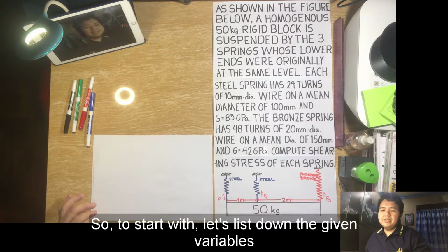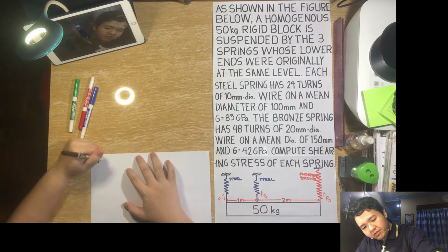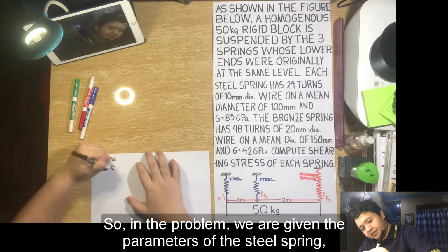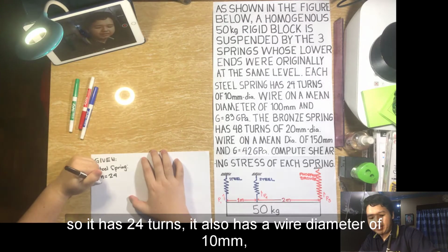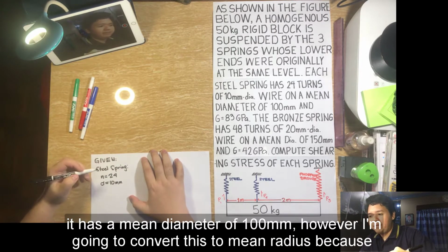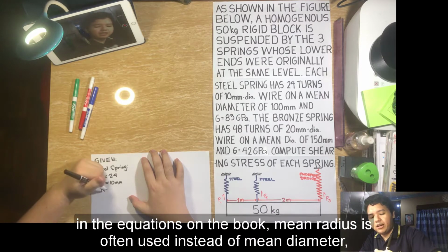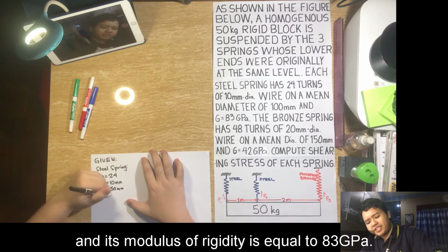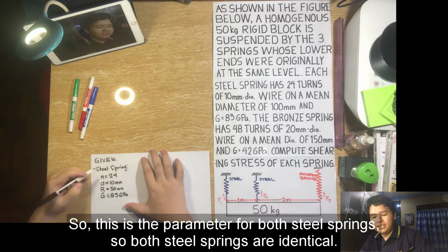To start with, let's list down the given variables. In the problem, we are given the parameters of the steel spring. It has 24 turns. It also has a wire diameter of 10 millimeters. It has a mean diameter of 100 millimeters. However, I'm going to convert this to mean radius because in the equations in the book, mean radius is often used instead of mean diameter. So mean radius is 100 millimeters divided by 2, which is 50 millimeters. And its modulus of rigidity is equal to 83 gigapascals. This is the parameter for both steel springs.